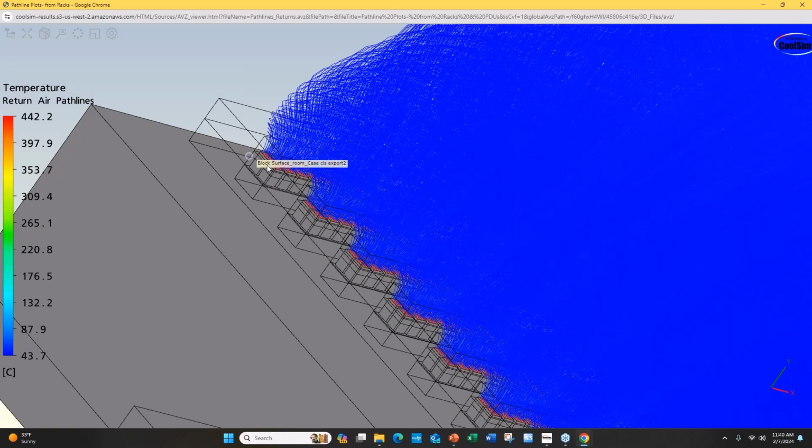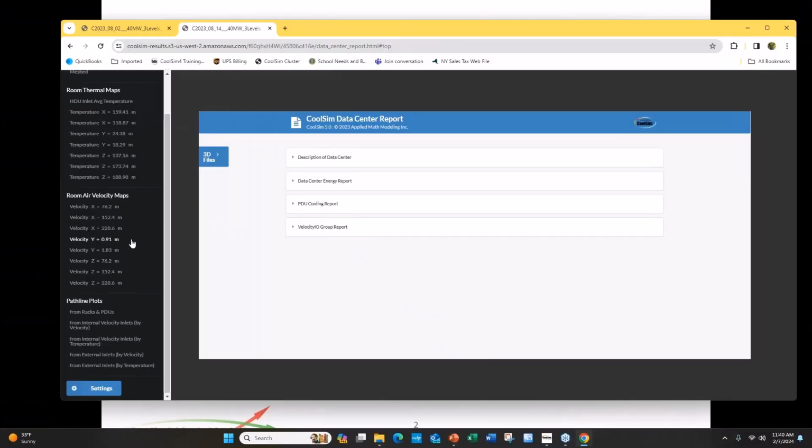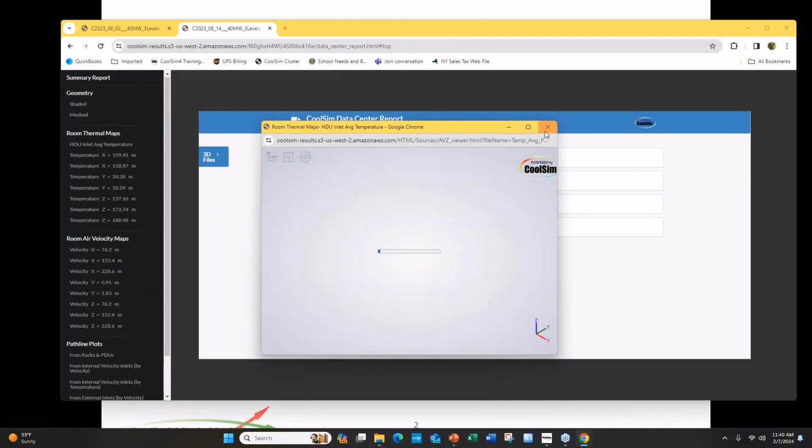This is a separation plate between the hot and the cold. Now that's expensive because that doesn't have any percent area open and you've got to worry about water. So you might want to put a perforation on that. I can't remember if we perforated it or not, but putting a plate there will reduce it and improve your total outcome. And then it becomes a question of cost.